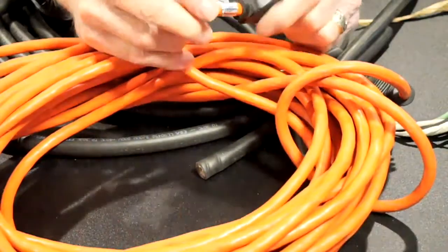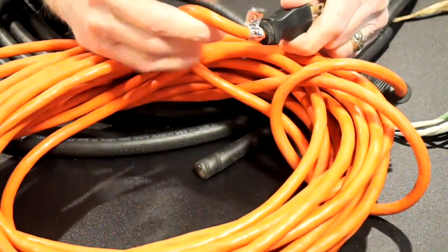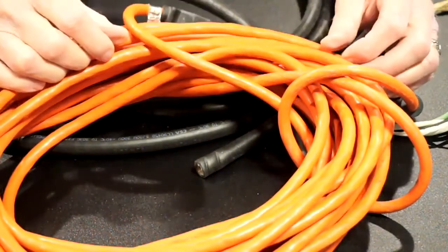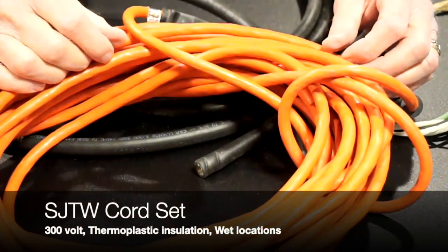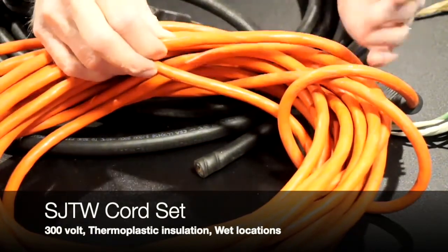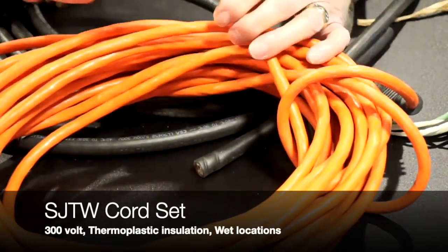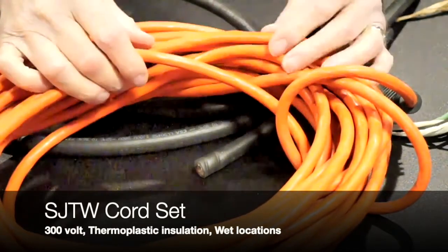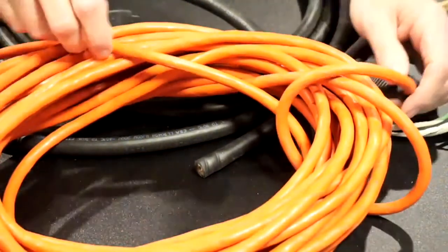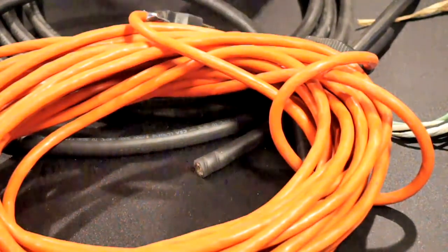One of the most important things probably on this cord set is it does have the UL label on it. You'll find on the outer jacket, it's going to say SJTW. So it is SJ, rated for 300 volts, T, a thermoplastic type insulation over the conductors on the inside, and W, this one is suitable for a wet location. So that is our flexible cords and flexible cables. Taking a look at them.